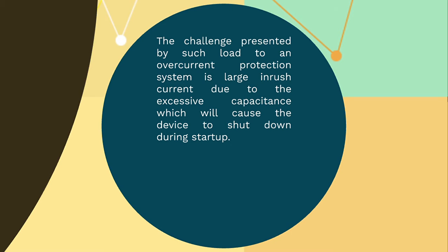Challenge. The challenge such a load represents to an overcurrent protection system is large in-rush current due to the excessive capacitance, which will cause the device to shut down during startup.